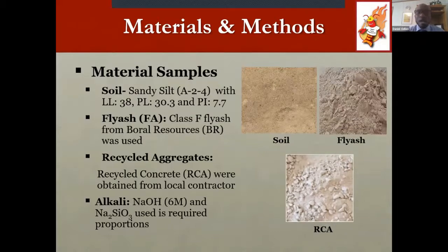We also sourced our fly ash from Boral Resources Limited, and the recycled aggregate was gotten from a local contractor in Louisiana. As we all know, most fly ash products are non-cementitious in nature, and as a result they require activation by an alkaline solution to be able to form a proper binder. The alkaline solution we're using is sodium hydroxide of 6 molarity and sodium silicate.